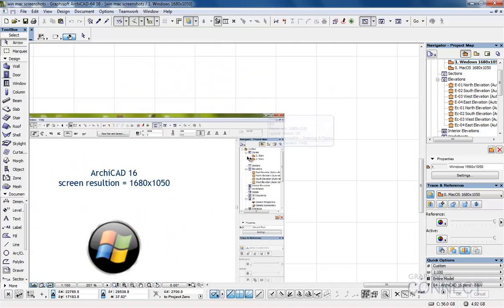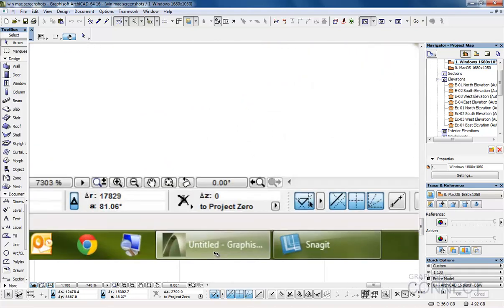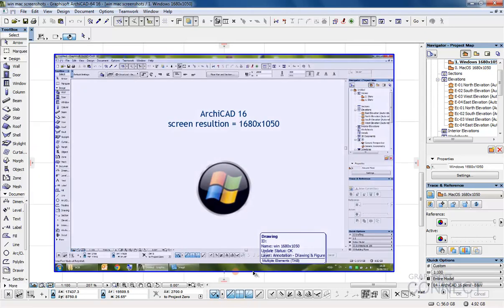Quite usefully, the zoom, if you put the mouse on a particular point when you zoom in, let's go for the ArchiCAD down here, it actually zooms in and centres on that particular area. One other thing you can do with the mouse wheel is just double click, and that does what's called fit in window, and it basically takes whatever is on screen and fits into the window.